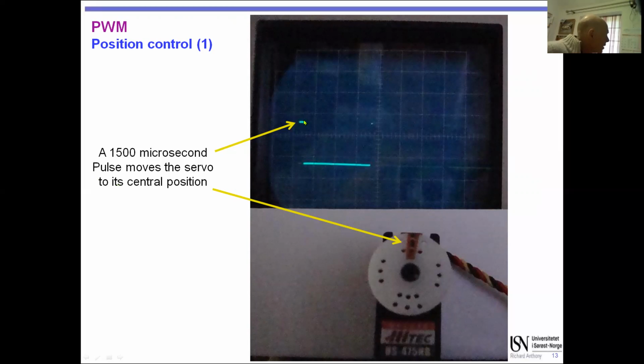That's basically 1.5 milliseconds, and that's 18 milliseconds, and that is the beginning of the next pulse. All right, I've set the oscilloscope to show just exactly one pulse, but because of the limits of my old oscilloscope, I can't. But it's useful to have that because that shows me that's basically that bit being repeated there.